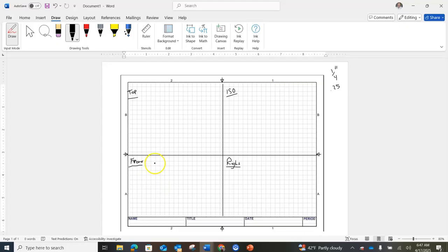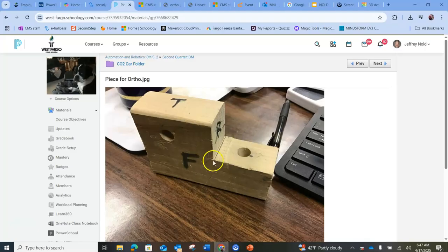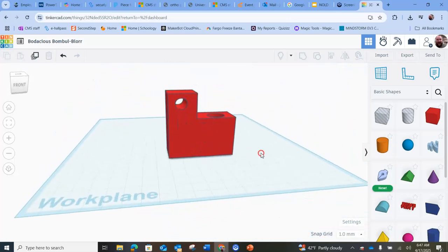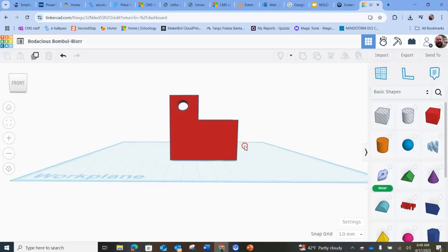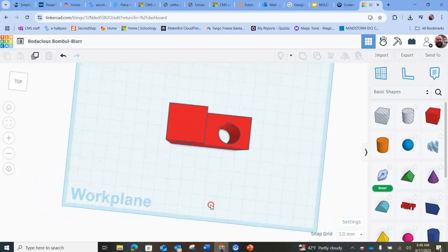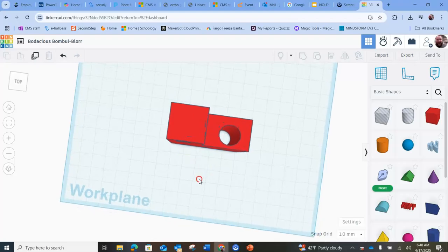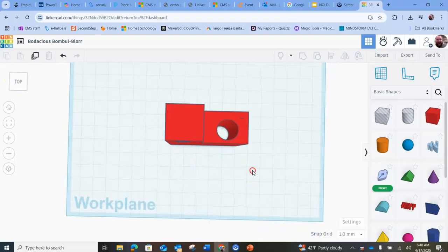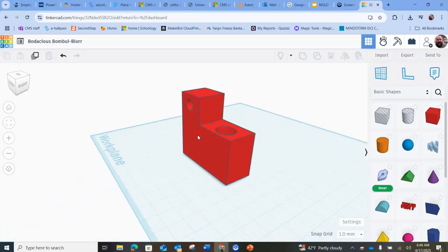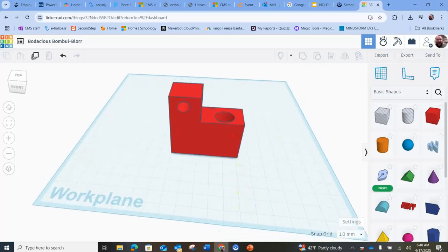All right. So when you draw this out, draw the front side of that shape, and remember the shape we're using is this guy. So to give you a better view, I drew this in. This is what it looks like in a 3D view. So what we're trying to represent is the front view that looks like this. Remember, we can't see that hole there. And then when we draw the top view, we can't see the hole here. And then on the right side, you can't tell there's holes on there at all. Okay? So that's why we do this overall.